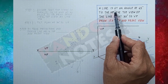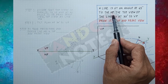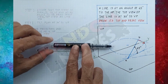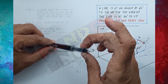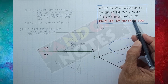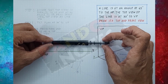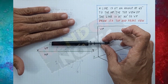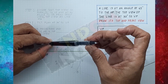A line is at an angle of 45 degree to the horizontal plane, which means there is a line and this is a horizontal plane. It is at an angle of 45 degree to the horizontal plane. The top view of the line is at 30 degree to the vertical plane. So if I see this is a line which is parallel to the vertical plane and parallel to the horizontal plane. Now it is at 45 degree to the horizontal plane.